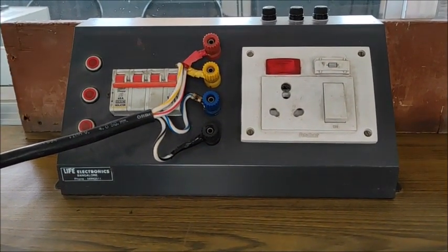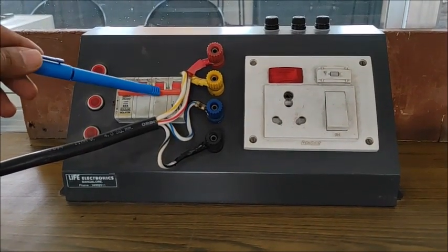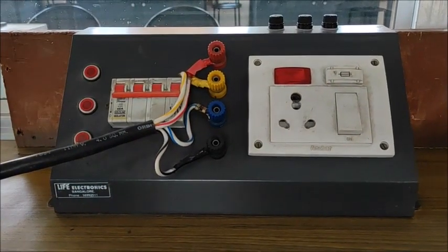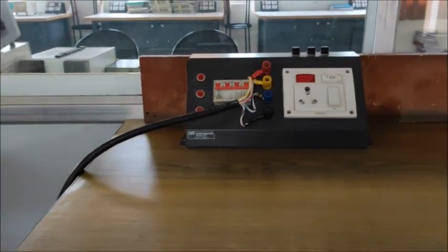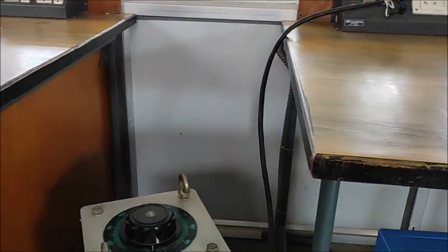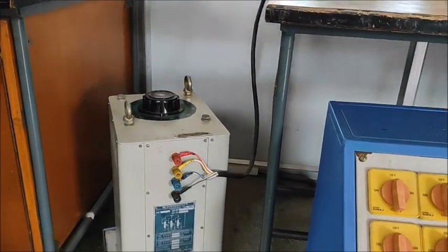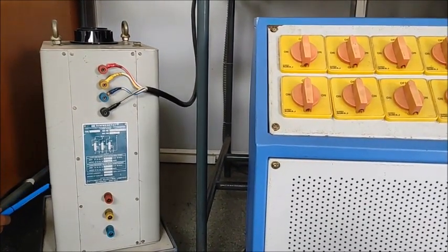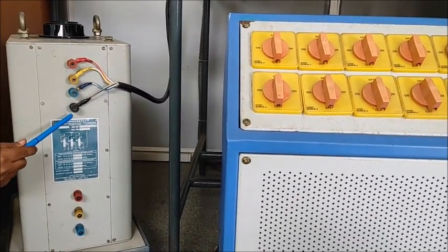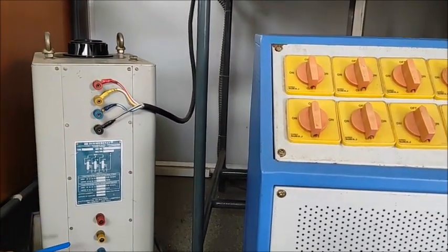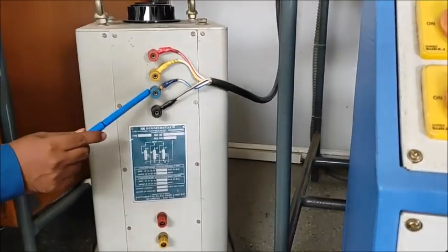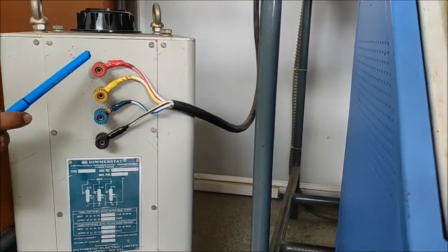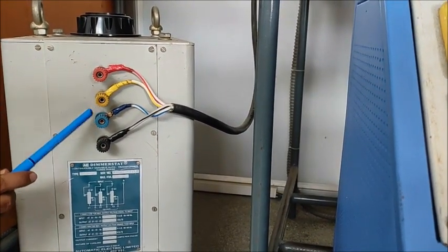So please remember, whenever three-phase comes into the picture, we have an arrangement called a triple pole single throw switch along with the RYB supply. Next, we shall look into another important piece of equipment required for our connection, which is an auto transformer. This is a three-phase auto transformer. As you can see, these terminals are the input terminals of the auto transformer, so that the power supply from the switchboard, which I have already shown, is taken. We have connected the power supply from the switchboard to the auto transformer input.